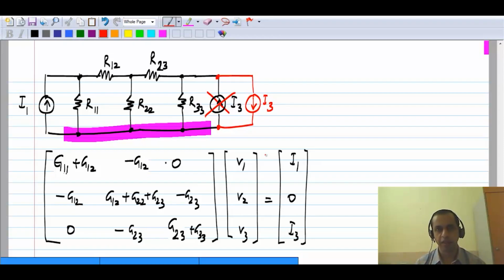We have made changes to the independent source, so this will change only the right hand side of the equation. And again, the answer is pretty clear. This element, which was the total current being pushed into node 3, was I3 and now it has become minus I3. That's all, and that's pretty obvious because we simply reversed the direction of the current source.